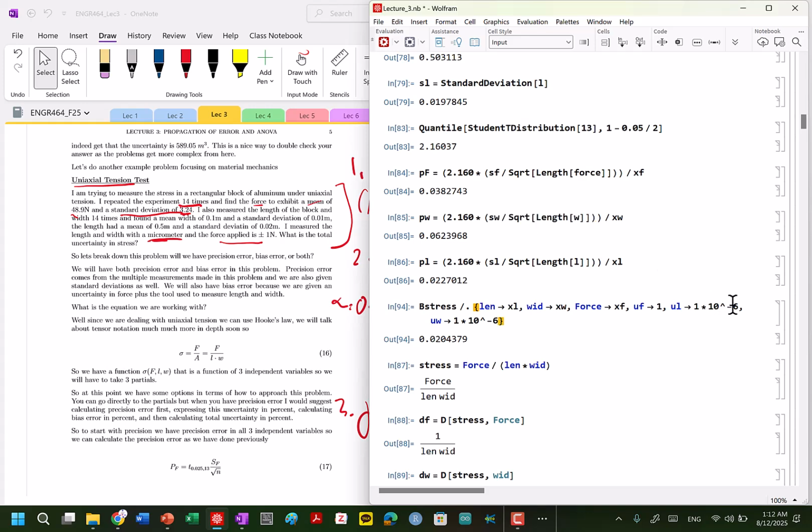Let's say, for example, I used a ruler, so minus 3, to make these measurements. In that instance, what if I do minus 2? You see here, if I use a ruler with basically centimeter tick marks, now what's dominating? That bias error. Now, I could improve that simply by just changing my tool. It's really hard to fix this uncertainty here. You're probably going to have to do more measurements, and you are going to hope that standard deviation doesn't grow as your number of measurements grows as well.